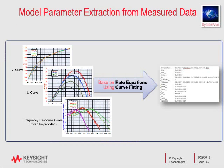So what we do is we take VI curves and LI curves typically, and also, if we have it, the frequency response curves, and use that information and some curve fitting algorithms to produce a set of coefficients that can then be used by the target VCSEL. And interestingly enough, if you had implemented this model in a SPICE environment using the same kinds of equations, this data would be equally applicable there. This is not a special set of data. It really does apply to this rate equation model, which could also be used in a SPICE environment if you have the same model there.